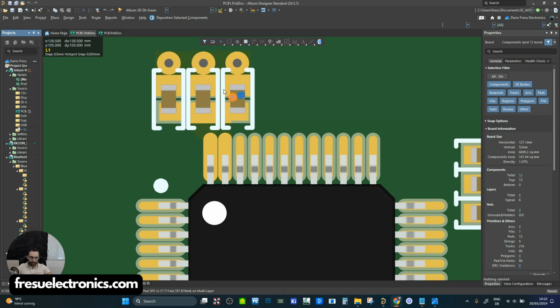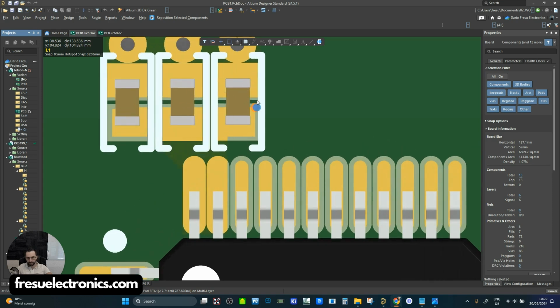So now, talking about the inductance, where is this inductance really coming from? This inductance is coming, first of all, from the package itself, so from the package of the capacitor. This will have quite some importance when we are selecting which kind of package we're choosing, if it's going to be a through-hole component or if it's going to be an SMD component.